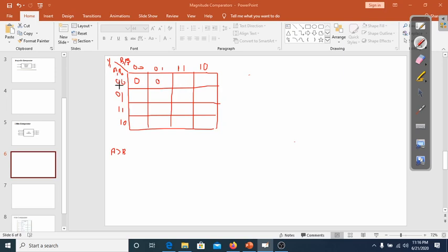So here it is obvious A is less than B, A is 0 whereas B is equal to 3. Here again the output is 0. So 0 1. So A is 0 1 and B is 0 0. So here A is greater than B. So I will plug in 1. And here 0 1, A and B are equal. So this is 0, 0 1, 1 1. Here B is greater. So I will put 0, 0 1, 1 0. Here A is less than B.